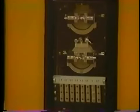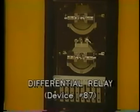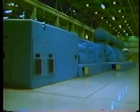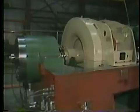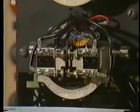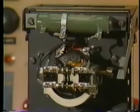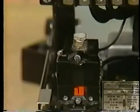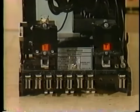One of the most sensitive methods of protection is provided by the differential relay, device number 87. Indeed, this is usually the first choice for protection of such items as generators, transformers, buses, and large motors. This is a typical example of an electromechanical differential relay. Its main components are the differential unit, restraining coils, trip contacts, harmonic restraint unit, instantaneous unit, and targets. We'll see what these items are for in a moment.